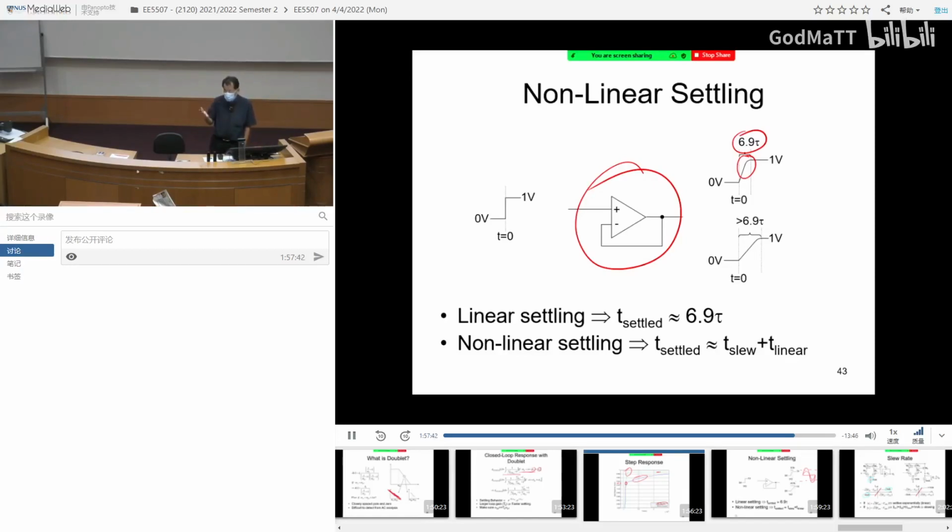In any design, by now you know, you always determine the tail current. So when you switch from one side to the other, the current is actually fixed. When you switch the voltage, you basically just steer the constant current to either this path or the other path. So the amount of current that you can achieve is always constant.